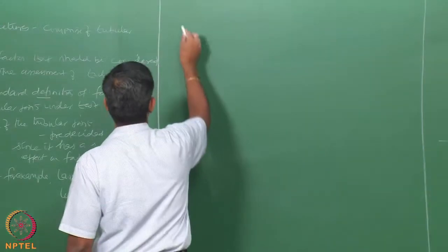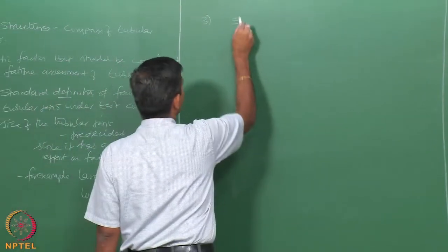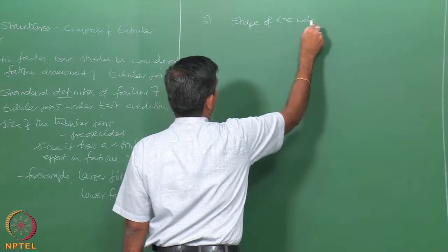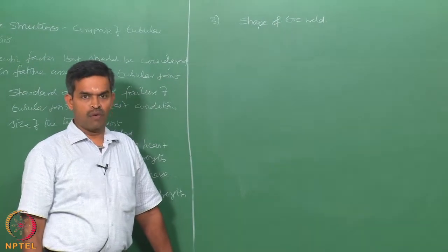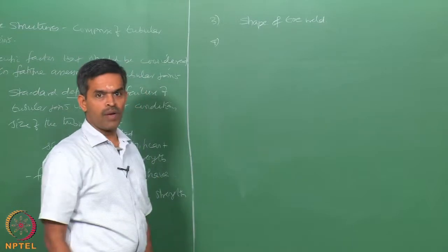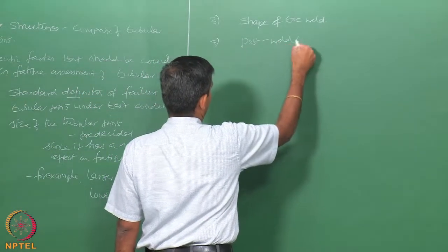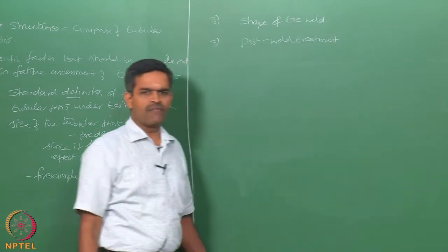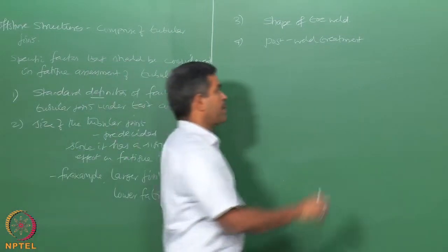Third factor could be the shape of the toe weld, which is also important in estimating the fatigue behavior of welded joints. Fourth could be the post weld treatment. This can significantly affect the results of a fatigue assessment and should be stated prior to the test.